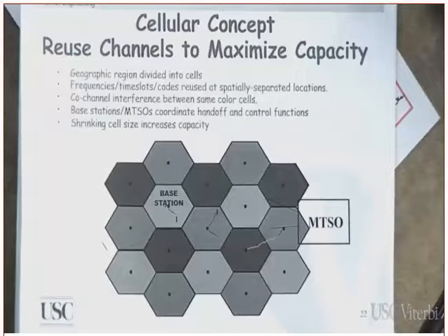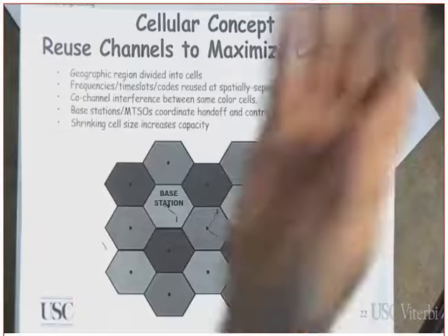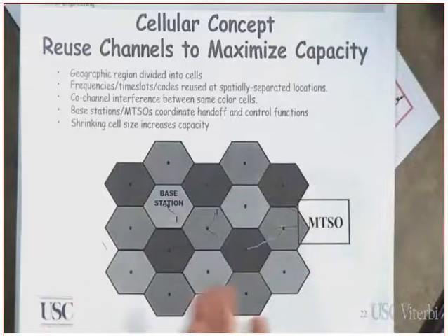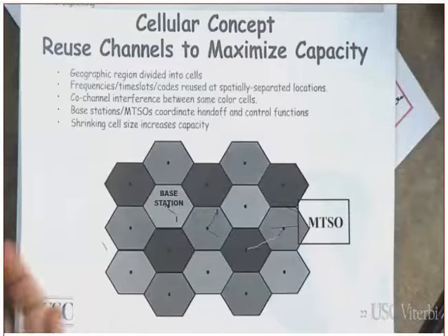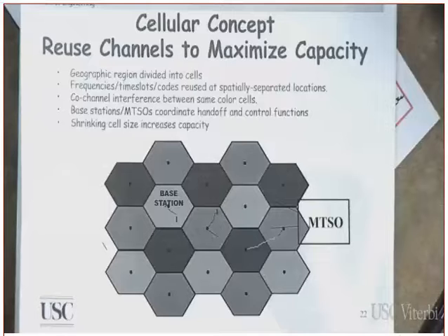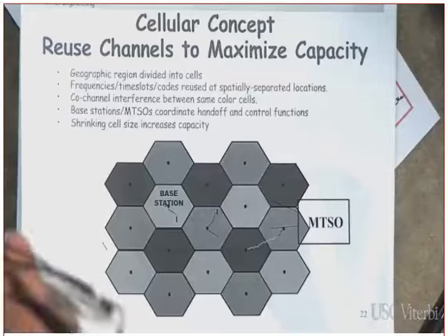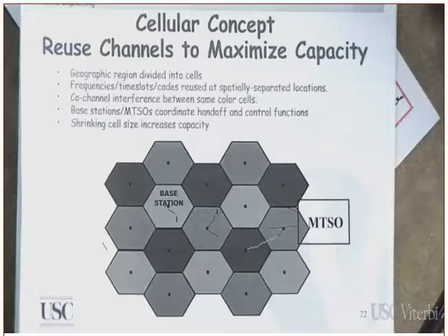However, they are orthogonal when they leave the transmitters. When they reach the receiver, they are no longer orthogonal. They are going to lose their orthogonality. And if they lose their orthogonality, is that going to be a co-channel interference? That is going to be a co-channel interference because you are transmitting using the same frequency. Clear?